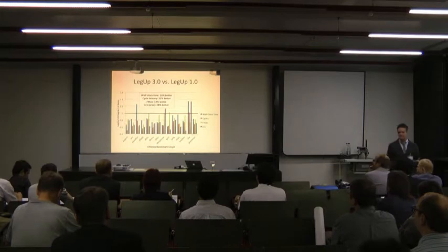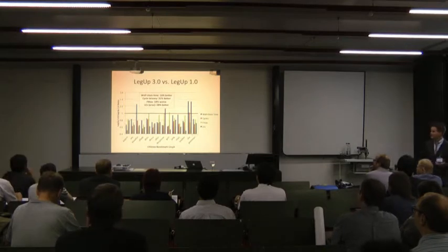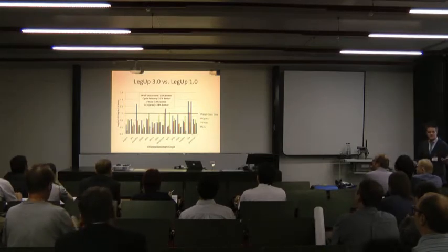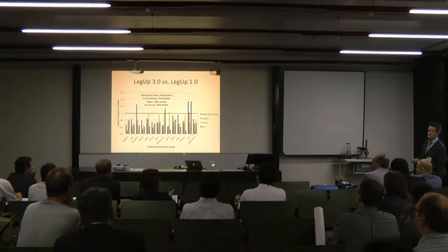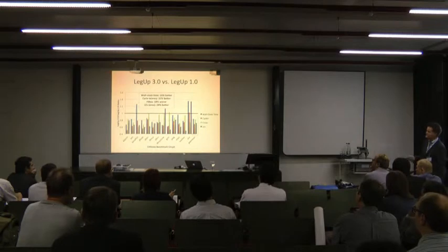Now, our most recent public release is LegUp 3.0 from last year. And what do the results look like in 3.0? Here you see the CHStone circuits in four bars: wall clock time, number of cycles it takes to do the circuits, Fmax, as well as the number of logic elements. And what you can see, wall clock time, we're about 16% better, cycle latency, 30% better, Fmax, worse, okay?